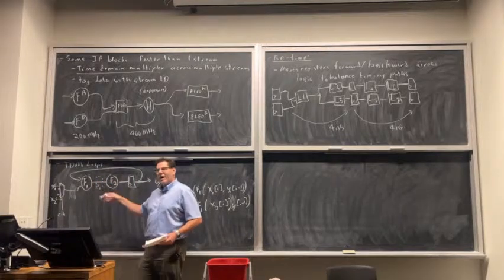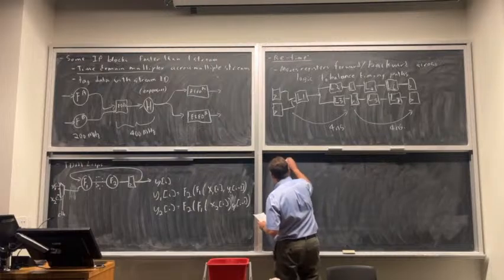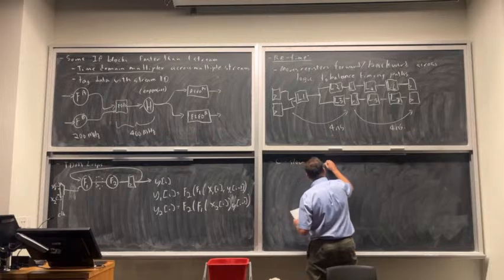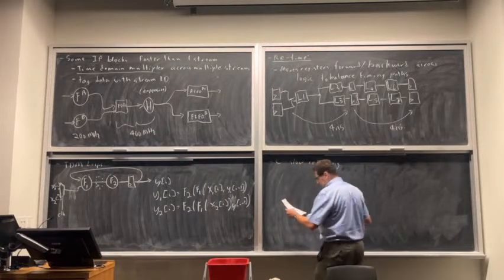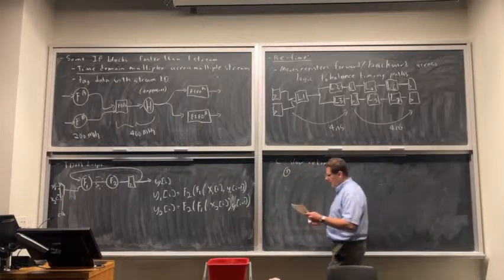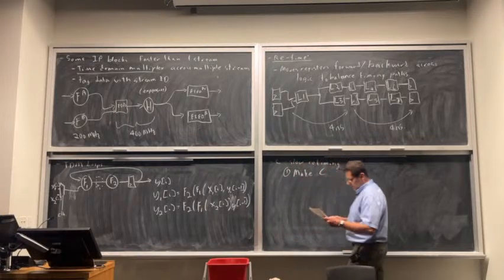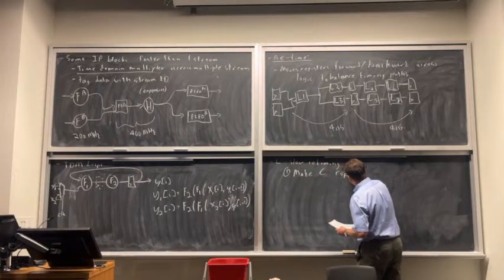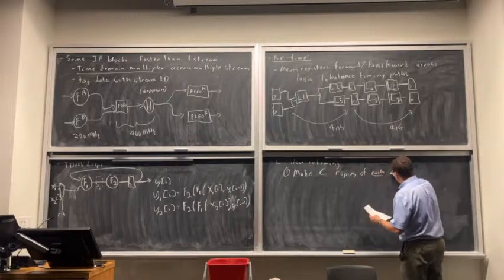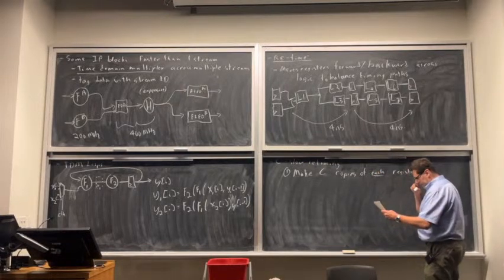Okay, so this technique of time domain multiplexing to allow deeper pipelining has a name. It's called C-slow retiming. And it's a mechanical procedure you can apply. So you make C copies of each register.